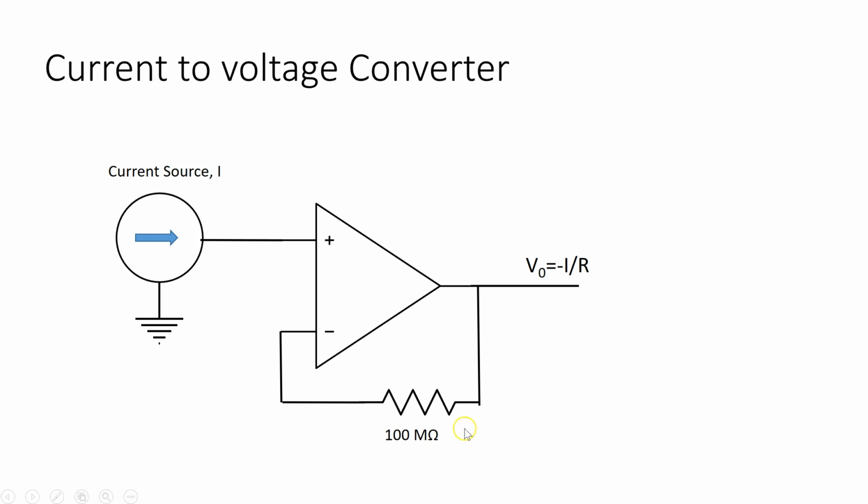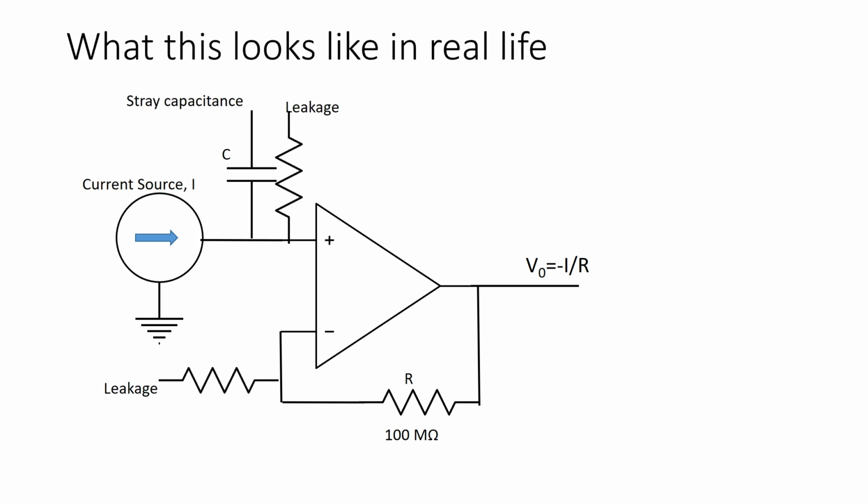So this then is a low current amplifier, and it looks very pretty like this, but we have to be careful. Since the currents are very small, any resistance, like a fingerprint on the circuit board, can generate leakage current into these inputs, and stray capacitance really matters.